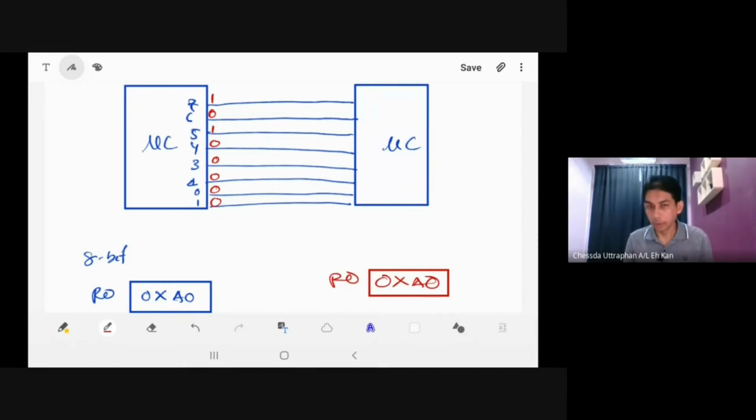All right. So sending data from one microcontroller to another microcontroller or other devices is actually very easy. Connect straight away. And this is called parallel data communication because we send data in parallel. If our data is 8-bit, we send 8 bits at a time, right? When new data comes, A1, for example, the line will be A1, and the second microcontroller will receive A1.